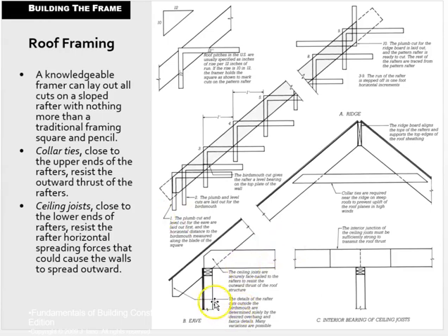So here we are up at the roof again. The stud wall comes up, double top plate. We see the sheathing on the outside. We have our ceiling rafters coming across. They're not really a major structural player, except that they are holding up drywall. Typically the loads from the snow would be coming down on the rafter and then being transferred down into the wall. And then here we see collar ties.